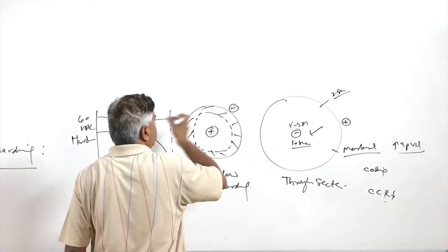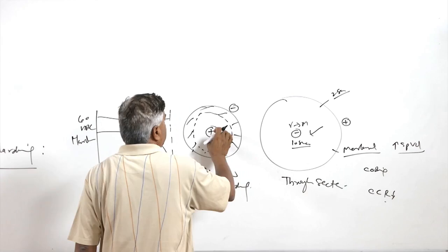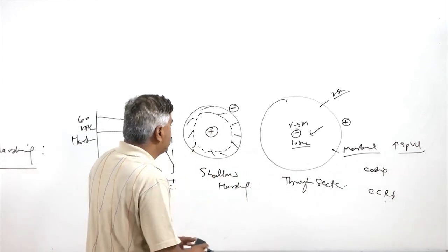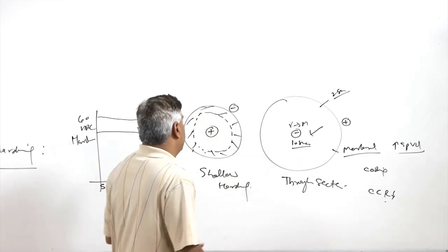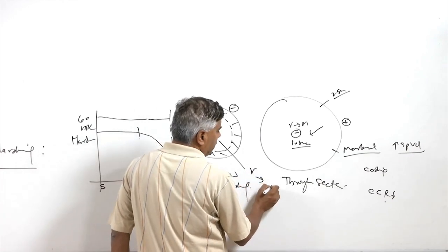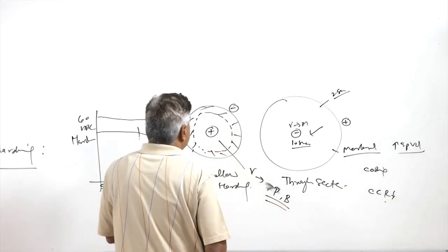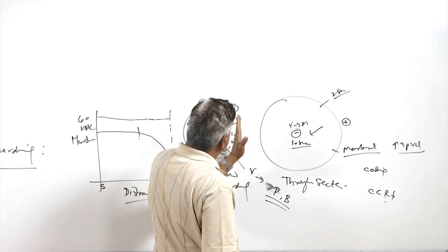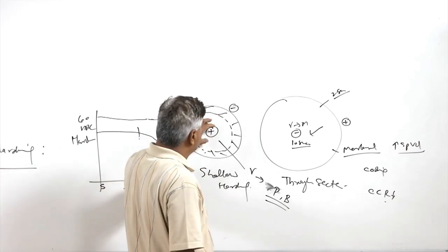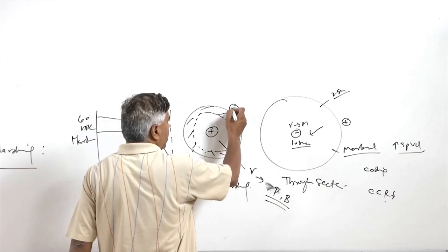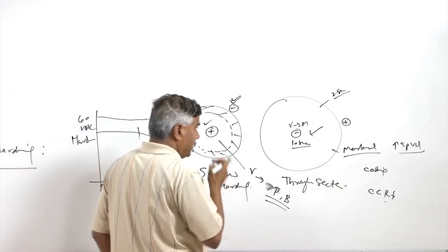In the shallow hardening, the surface gets hardened, and subsequently the transformation at the center does not occur into martensite; from the austenite it occurs into pearlite or bainite. Since the transformation at the surface occurs with an increase of specific volume, but there is no major change in specific volume at the center, we get compressive residual stresses at the surface and tensile residual stresses at the center.